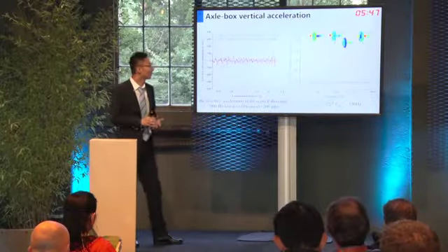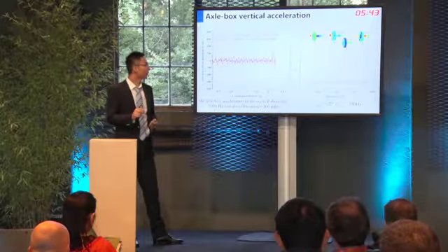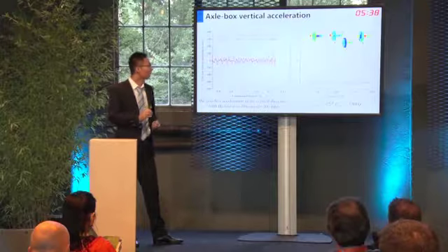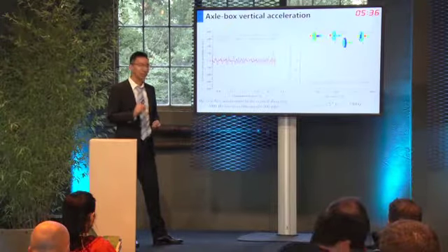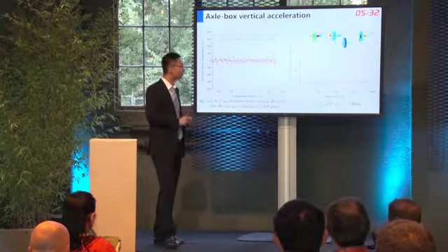And as we mentioned before, the first order decoupling frequency of the resilient wheel is about 390 Hertz, and the theoretical vibration isolation frequency of the rubber is about 550 Hertz.